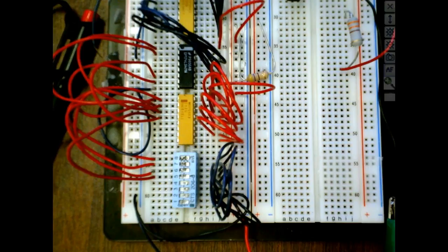No, it means it's low active. It's not a regular A. So the output, we're using a common anode display, right? So we turn them on with lows. We have two ways we can indicate lows. We can indicate it with a line above it, low active, or we can even indicate it with a dot. The pin out shows it as not A, or low active A, but how does the actual schematic indicate the low active outputs?